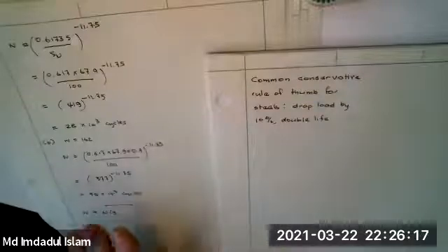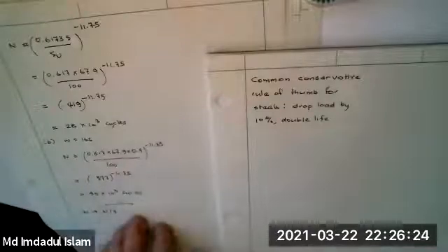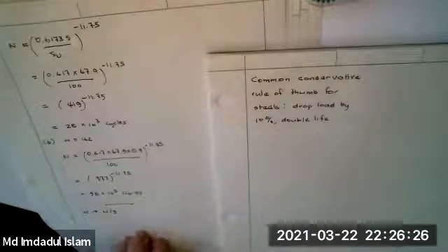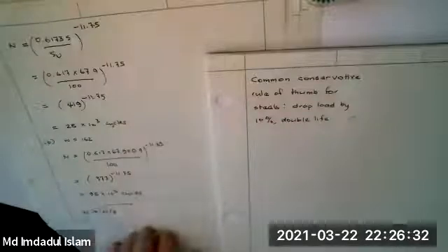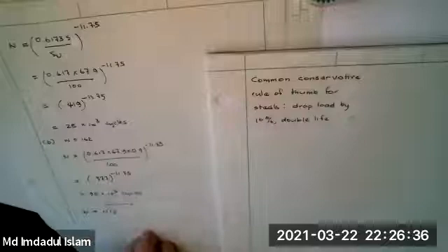Okay, there's a bit of data fitting here. Just use these formulas. You don't have to derive them. Just use the formulas we've got here, and that's what you use here. When you get up in practice, they'll have their own formulas. They'll have slightly different numbers. They'll know their steels better. I'm just doing a generic steel here. But this will show you how to use fatigue life calculation, hopefully.